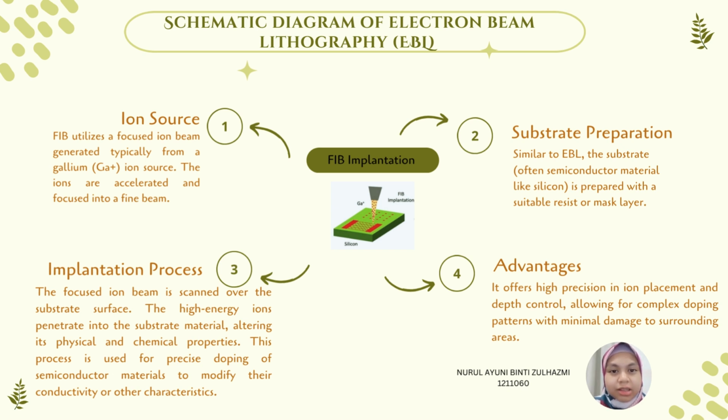This process is used for precise doping of semiconductor materials to modify their conductivity or other characteristics. Fourth, advantages. FIB implantation offers high precision in ion placement and depth control, allowing for complex doping patterns with minimal damage to surrounding areas.